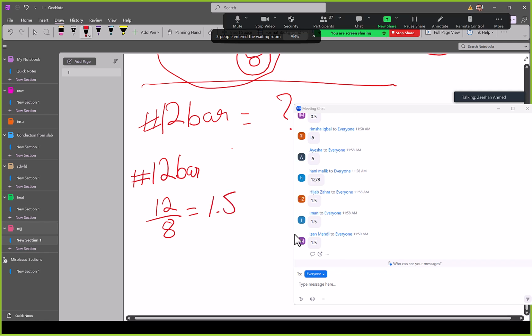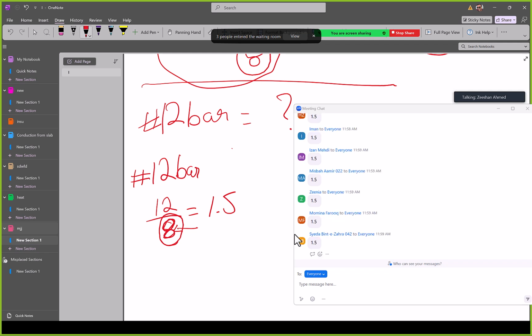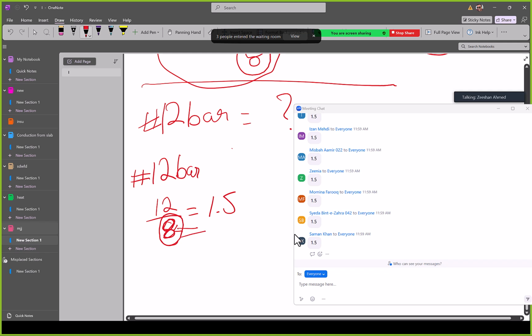Very good. So this 8 is somehow, strangely, a very important number in engineering. Very, very important number in structural engineering actually. 8 is the minimum number of rebars that you use in pile foundations. 8 inches is the minimum width of the beam that you can use. The American engineers love 8. So 8 and 12, we use these again and again in a lot of places.